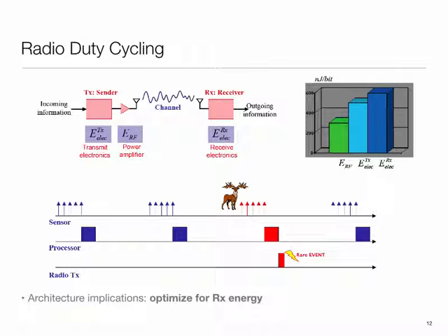Typically, these kinds of systems operate such that they wake up once in a while, collect some samples from the environment, and then process them. If there is something interesting, they send an event report out. If there is nothing happening, no event report goes out. In this case, the duty cycle is going to be sized so that your probability of a missed event is low. The number of samples that you collect has to be enough so that you can get a reliable decision.